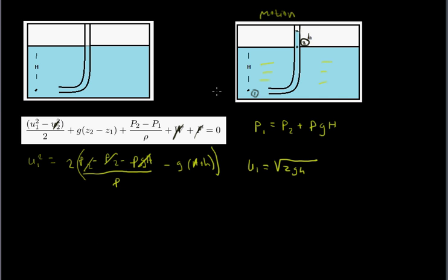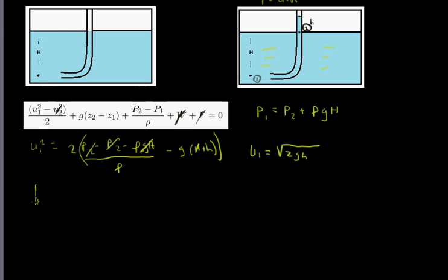Okay, so let's go ahead and do the problem if that is the case. So again, we're going to be using the Bernoulli equation, and we are going to cancel out the exact same things. And what we're going to end up with, so let's say, if you're measuring with a pressure transducer, what you're going to get is an expression that says P2 minus PATM, so it's going to be gauge, is equal to, so let's just look at this picture.